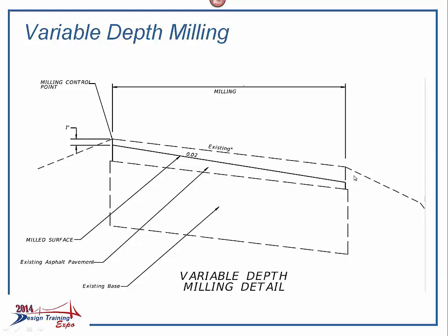First of all, this line that's in dashed here represents existing ground or the existing surface that's going to be sampled. When the subassembly is inserted, it's basically inserted at a point. That point is usually a profile grade line that is defined at an existing surface. So when you're targeting, the subassembly is going to insert just like a normal subassembly would. If you want all of your milling operations to start at the existing ground, you'd want your profile grade line to be designed right at existing ground. So you may do an existing profile right along the top existing surface of the earth.